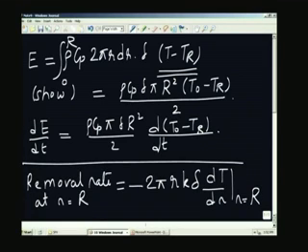What I am going to do is use the same expression which I had earlier and then obtain this particular thing. At any instant of time there is a certain instantaneous temperature gradient at r equal to R, and I will manipulate the equations. I will not show the intermediate steps. We can show that this is equal to 4 pi k delta multiplied by T naught minus T R.